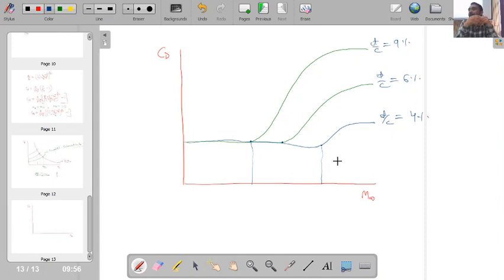So one way of achieving high speed flows: if we want the aeroplane to move at high speed, then our critical Mach number should be large, then only can I achieve a large free stream Mach number. So in order to achieve high speed flow, our aerofoil should be thin.